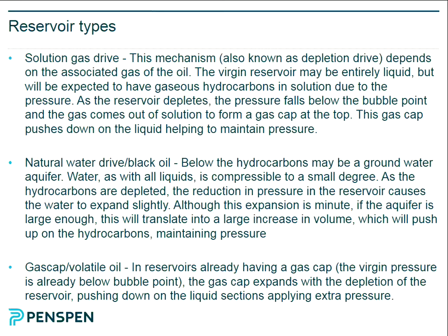So reservoir fluids. In terms of what you find in reservoirs, you get the hydrocarbons ranging from methane, CH4, to very, very high molecular weight components, complex, 40 plus atoms, and then you've got all the variations of those as well. So it's actually a very, very complex organic chemistry. There are 4 principal types of hydrocarbons: paraffins, saturated straight or branched chains, naphthalenes, saturated cycloparaffins, olefins, and aromatics.